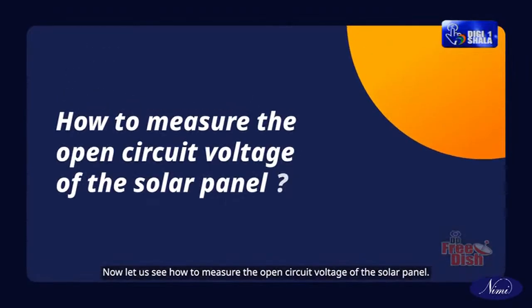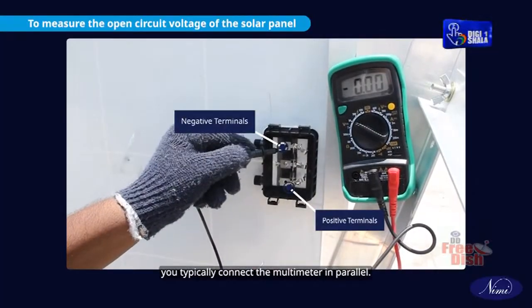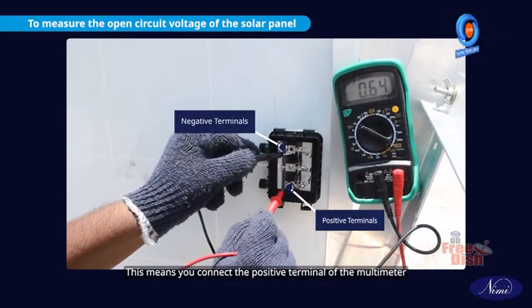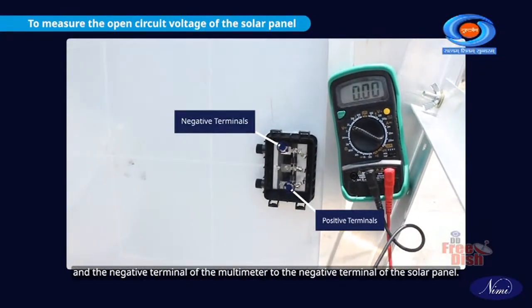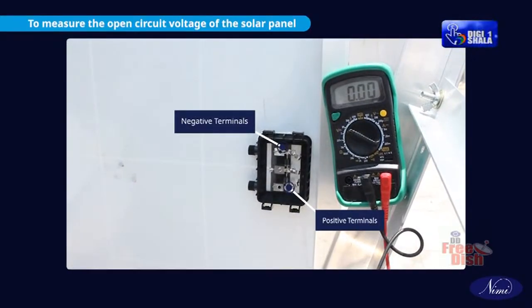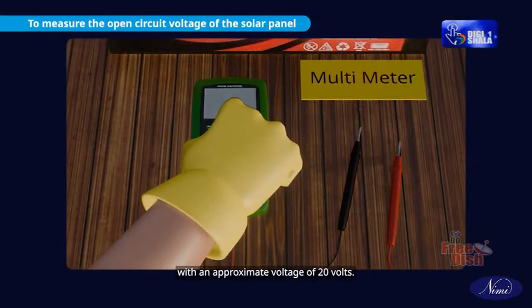Now let us see how to measure the open circuit voltage of the solar panel. When you are measuring the voltage of a solar panel, you typically connect the multimeter in parallel. This means you connect the positive terminal of the multimeter to the positive terminal of the solar panel and the negative terminal of the multimeter to the negative terminal of the solar panel. Set the multimeter in DC voltage measurement range with an approximate voltage of 20 volts.